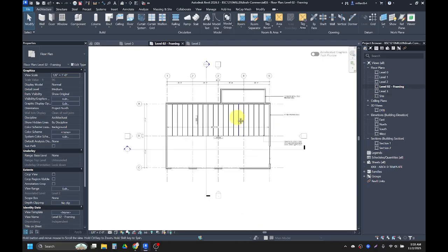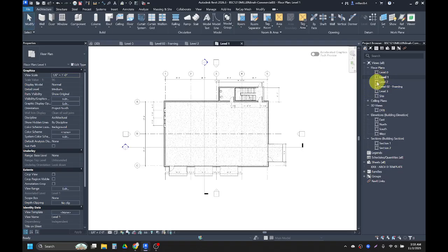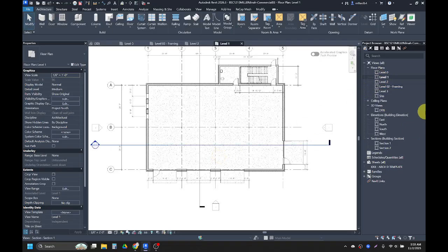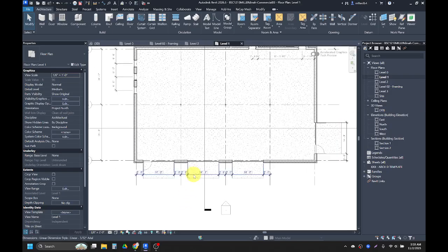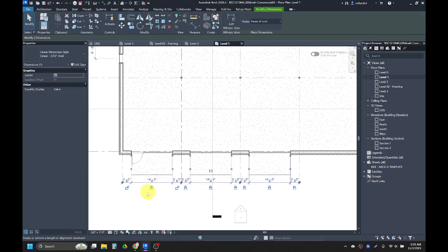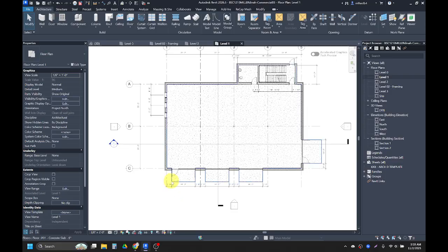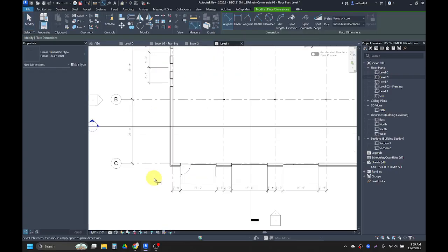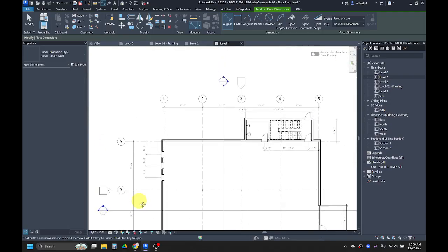My next view in my series is my level 1 floor plan. And so in the level 1 floor plan, we already have a few of our dimension strings. I'm just going to pull this one down a little bit for it, but we can continue adding on. Some of them we already made purely just from creating our floor plan and adding in our windows. But again, it's keyboard shortcut DI. And then I could go from C to that pad and then click over to place it.